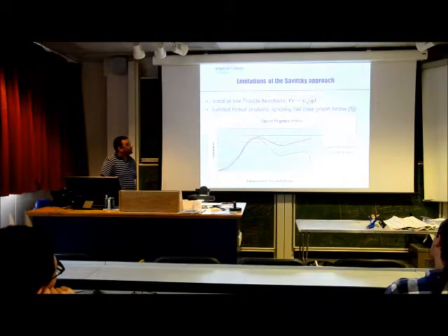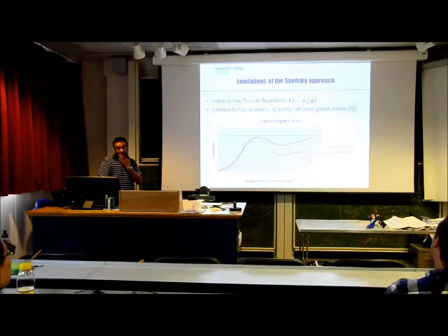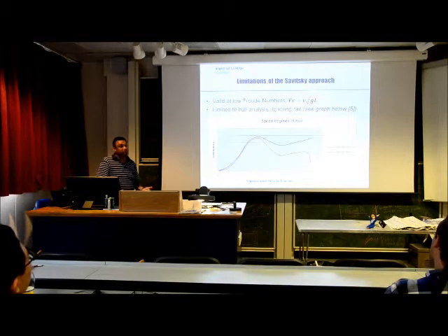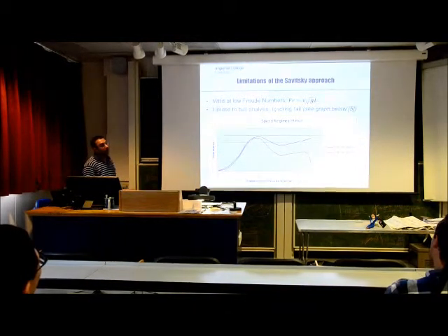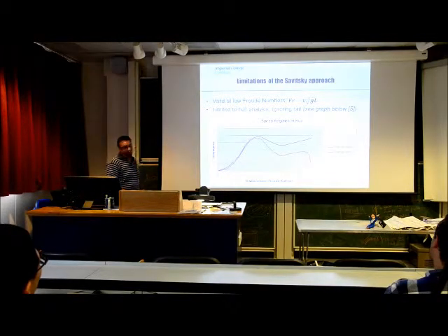The Savitsky approach is something that other research frequently refer to, but its limitations are that it's valid at low Froude numbers, which essentially translate into low speeds. And it's limited to the hull analysis. As I said, it's just accounting for forces that are acting on the hull.